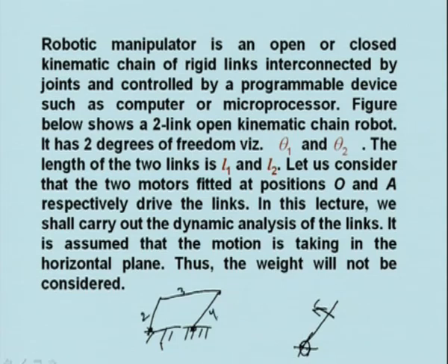You see that this chain is closed: link 1 starts at one point and link 4 closes at that point. So this is called a closed kinematic chain, and its degree of freedom is 1. That means if we give some rotation to 2, then we can know how much 4 will move.